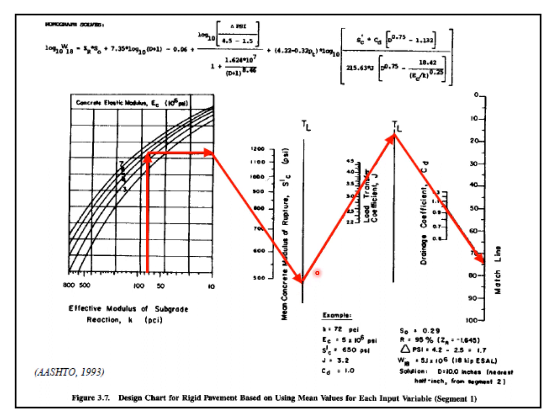Then look at this one. This one is meant for load transfer coefficient. Let's say the load transfer coefficient value is this one. So from this point we will draw this line in this way, and we will reach this turning line at this particular point. After reaching here, look at this one. This is the drainage coefficient.